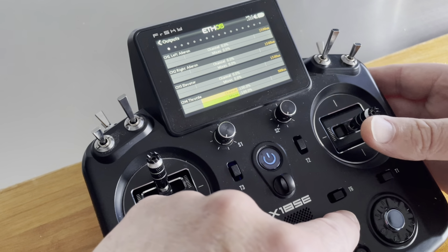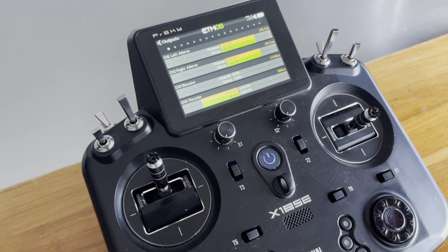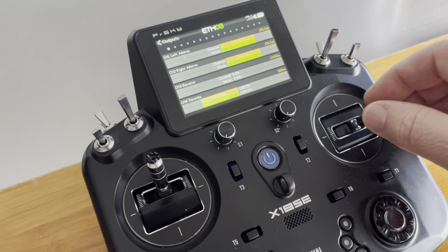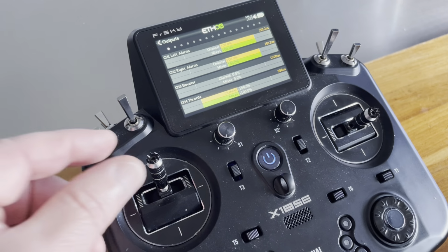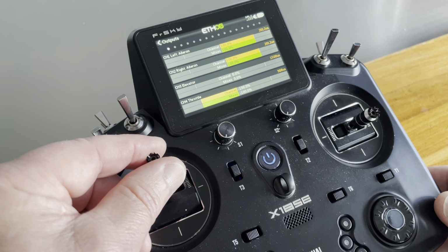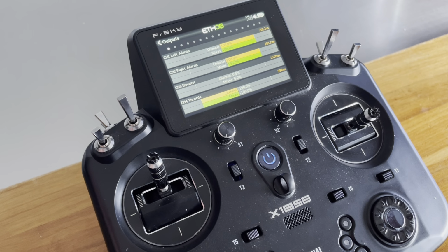But when we go into calibration mode, calibration on, the calibration mode takes over from all the other mixers that are in the program, and you can see now I've got no control of the ailerons. However, I've repurposed the throttle stick to give me 5 positions for that matching of the left and right ailerons and flaps.